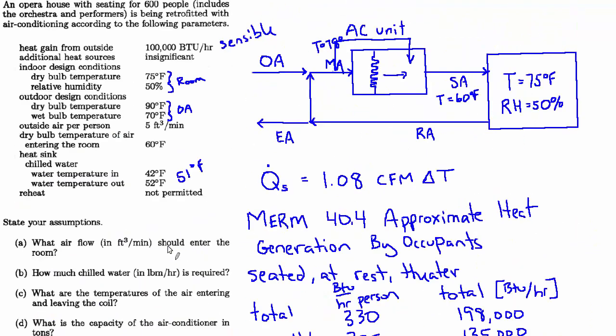But we also have to consider this outside air. Some of that cooling in the room is happening, but it's being wasted, and this is why outside air is a bit painful when it comes to operating efficiently, because you have this air that's 75 degrees. It's pretty useful. You could recirculate it and just cool it down a little, especially if it's a hot day. But unfortunately, you have to exhaust it and bring in this outside air, which is 90 degrees and has to be cooled a lot more.